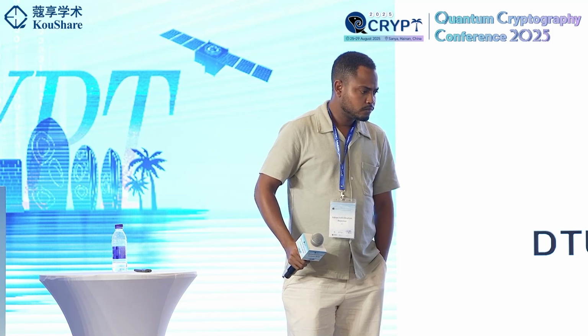A very nice talk. I see your S21 diagram, where the 3 dB bandwidth is almost 7 gigahertz. Sorry, I can't hear you. Transition speed. It's not clear to me what you are saying. Okay, your 3 dB bandwidth is almost 7 gigahertz, but you do experiments at speeds of 8 to 16 GBaud, and I'm confused. Why can this relatively low bandwidth lead to such high speed?